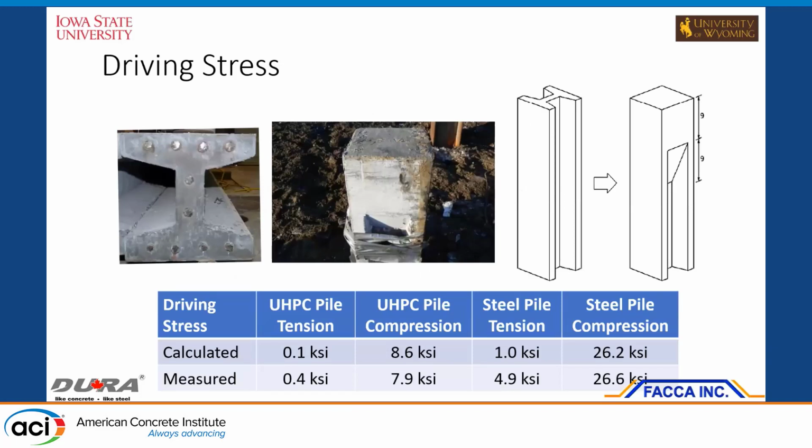One of the concerns we had at the time was that at the top, you would have less effective pre-stressing and your driving stresses could be high. So the very first pile we designed, we had a square section at the top just to eliminate that concern. Subsequent studies confirmed that the driving stresses right at the tip are actually lower than further down. So eventually we got rid of that.